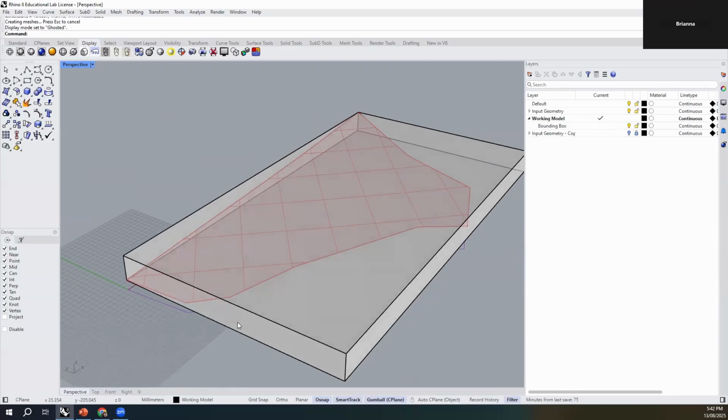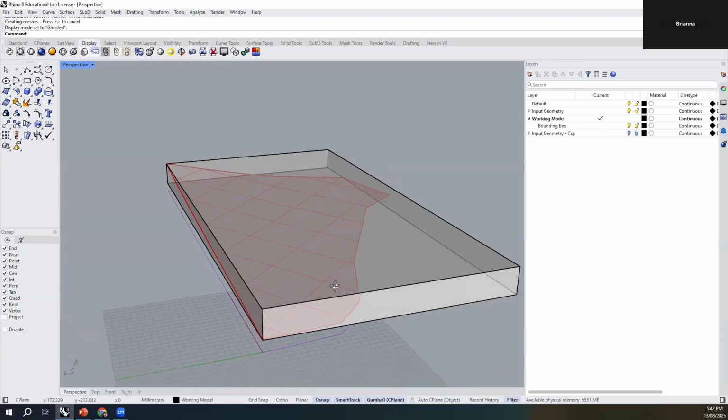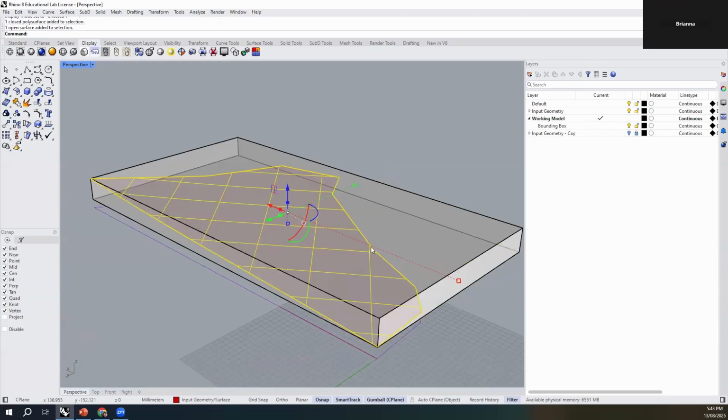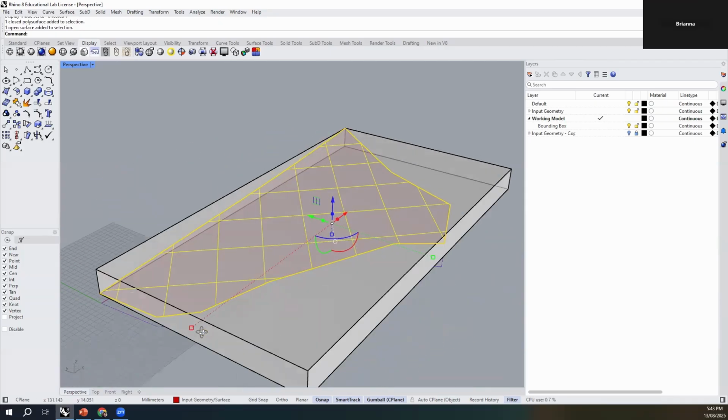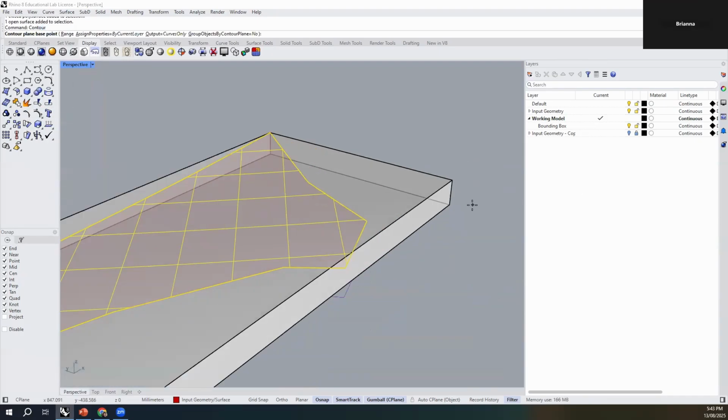I'm going to cover that in the next iteration of this session because we just don't have enough time. But for the time being, we'll just proceed with the idea that you just want to articulate a simple surface and maybe you're going to drop some objects or some buildings. So selecting my surface, I'm going to use the contour command, surprisingly. I'm going to select the base point of my bounding box on any corner and then the top point like that.